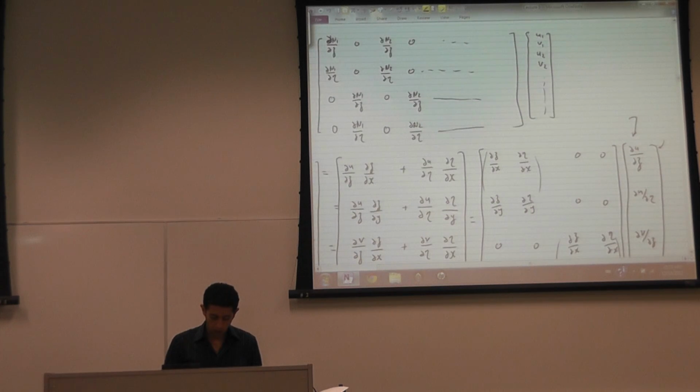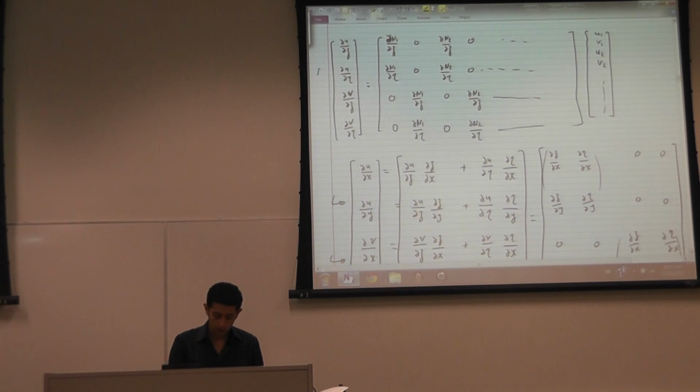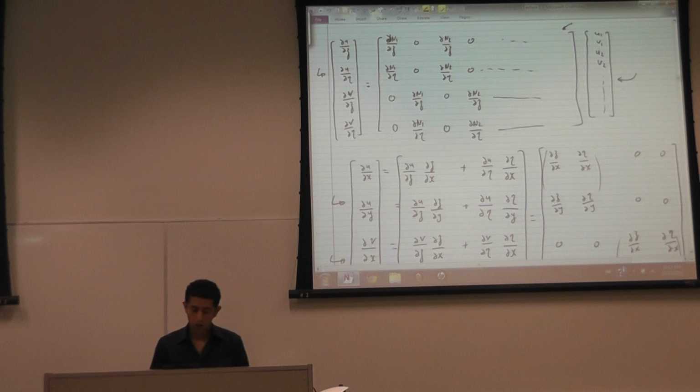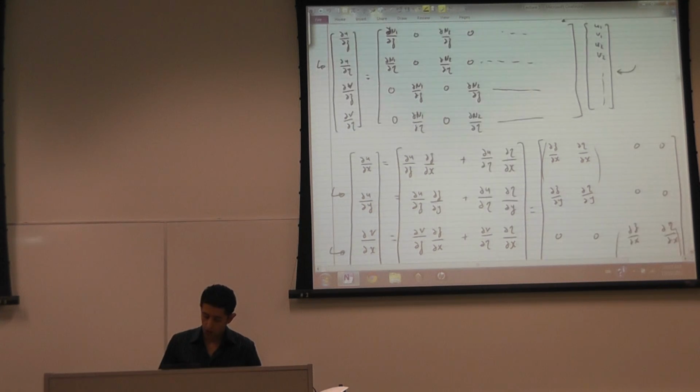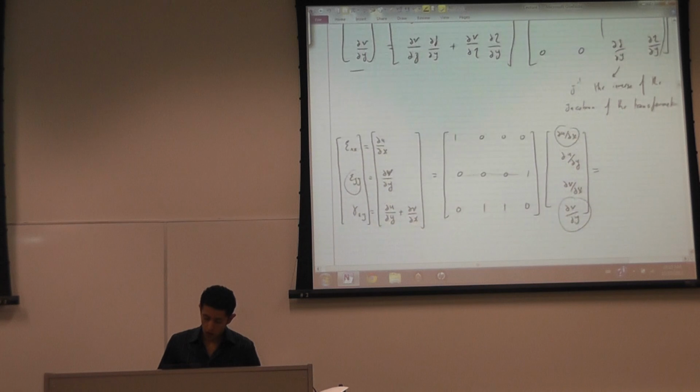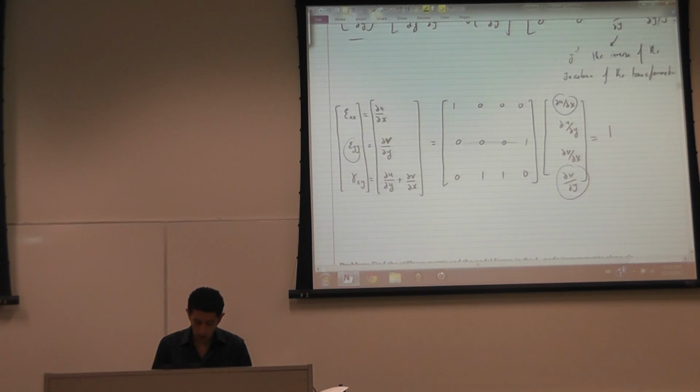And the derivatives of the perfect coordinate system are a function of the degrees of freedom of the element. And so this will be equal to a huge matrix B multiplied by UE. And this will be the degrees of freedom. And this matrix will be 3 multiplied by the degrees of freedom.